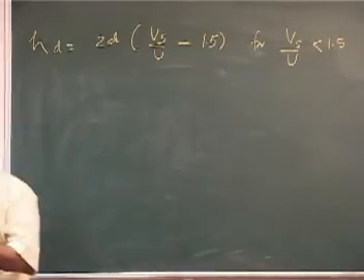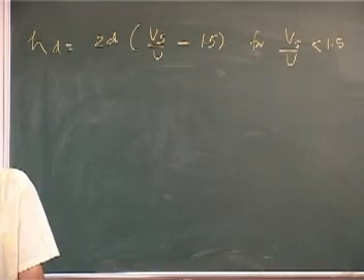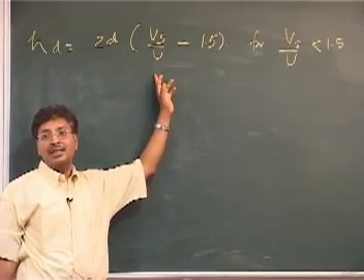This is the correction, and D stands for downwash. This is the correction you apply to your plume rise if the ratio of exit velocity to horizontal wind speed at the tip of the stack is less than 1.5. The correction becomes negative. See here, suppose your Vs by u is less than 1.5.